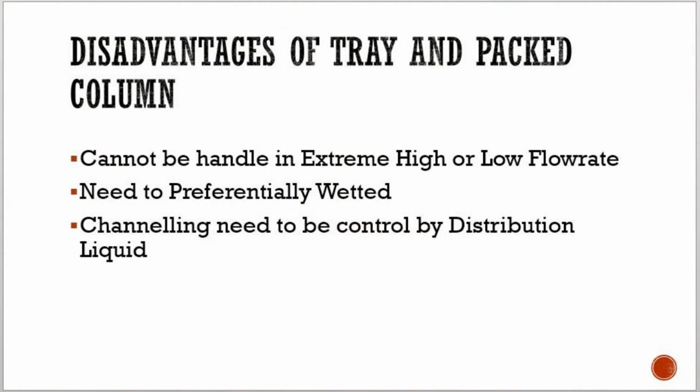Next, the disadvantages of both tray and packed columns: they cannot handle extremely high or low flow rates. The packing needs to be preferentially wetted to avoid reduction of the interfacial area to volume ratio. And lastly, channeling, which must be controlled by redistributing liquid.